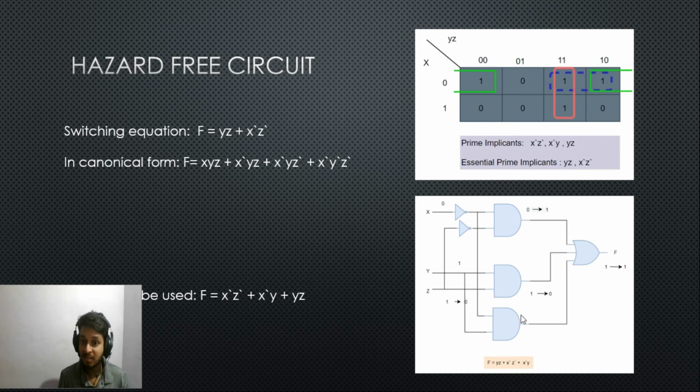So indefinitely the output is staying 1. So this circuit is staying away from hazard. So it's a hazard free circuit. So this is how we can solve the problem. Okay, that's the reason why we should have this also as a group, whichever the overlapping thing is.